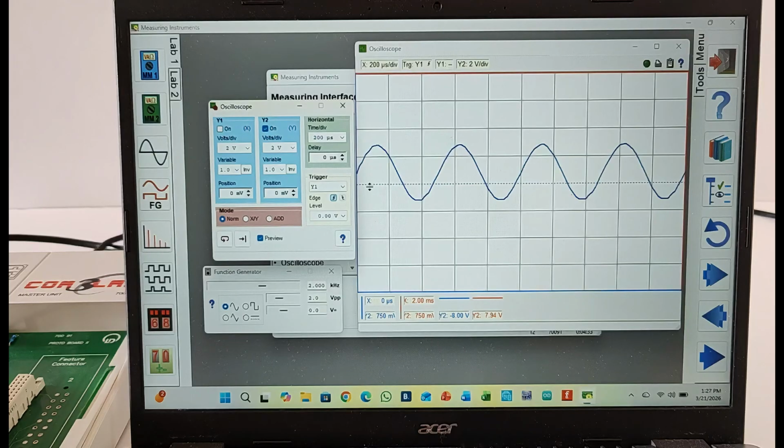You might be wondering why that happened. We already have a capacitor on the circuit, a 10 microfarad capacitor. The possible reason is that the value of the capacitor is not enough to prevent the DC offset coming from the function generator. So how do we fix this now? Let me adjust the display so that this will look better. Now let me do something first.